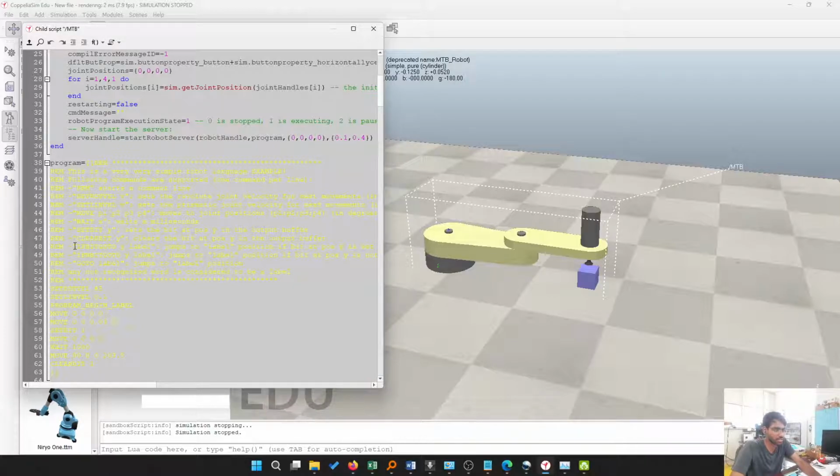Another thing is something called IF BIT GOTO condition. I'm coming back to the earlier point where I was saying, let's say we have a proximity sensor, and only when the object is there, it has to go and pick and do some routine, go to the left or go to the right. Those are basically routine commands to tell, okay, right with this instruction, left with this instruction. So how do we tell the robot that the proximity sensor has triggered, and now it should do something? There's something called the input buffer.